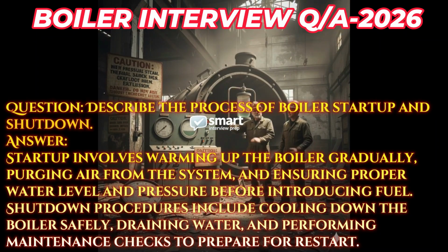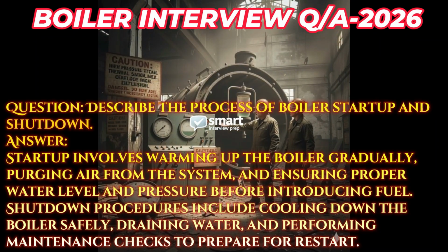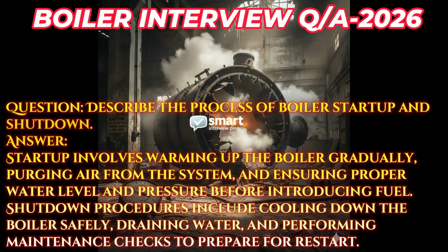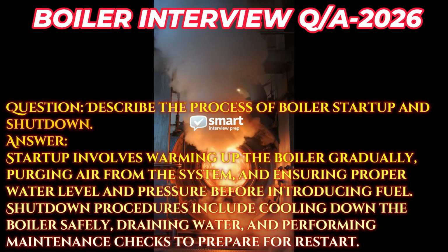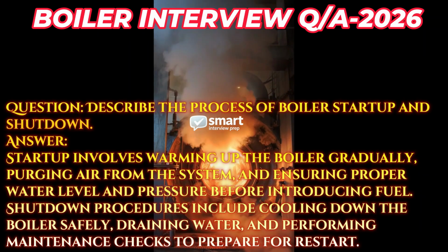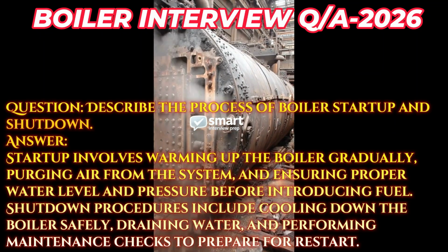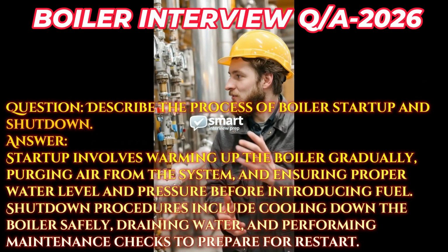Question. Describe the process of boiler startup and shutdown. Answer. Startup involves warming up the boiler gradually, purging air from the system, and ensuring proper water level and pressure before introducing fuel. Shutdown procedures include cooling down the boiler safely, draining water, and performing maintenance checks to prepare for restart.